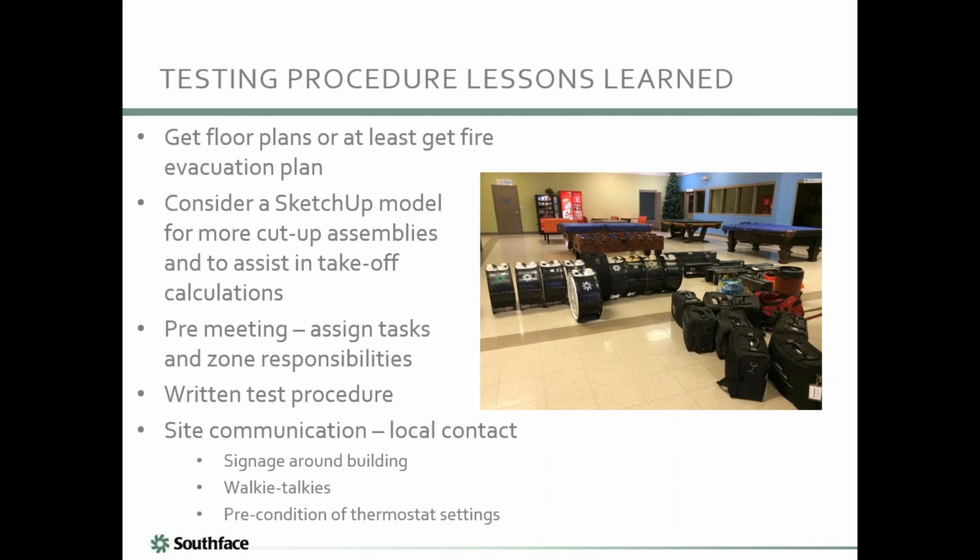And a very useful thing, and we have templates for this, we found it useful. We wanted to put the building back the way we found it. So we felt it was valuable to either take a picture of the settings on the thermostat, or better yet, just log it and make sure you put it back that way. If it's one thermostat, it's not such a big deal, but when you've got 15 thermostats and you're trying to keep track of all of this, it is a much bigger deal. So I think that was another big lesson learned.